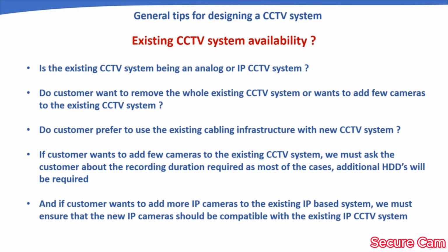And the last point is, if the customer wants to add more IP cameras to the existing IP based system, we must ensure that the new IP camera is compatible with the existing IP CCTV system. Nowadays, all IP cameras support the ONVIF protocol, but still we must ensure that the new IP camera's ONVIF protocol supports the existing CCTV system and we are able to get all the required features as mentioned by the customer. These are a few points and you can also add your own points while designing a CCTV system.